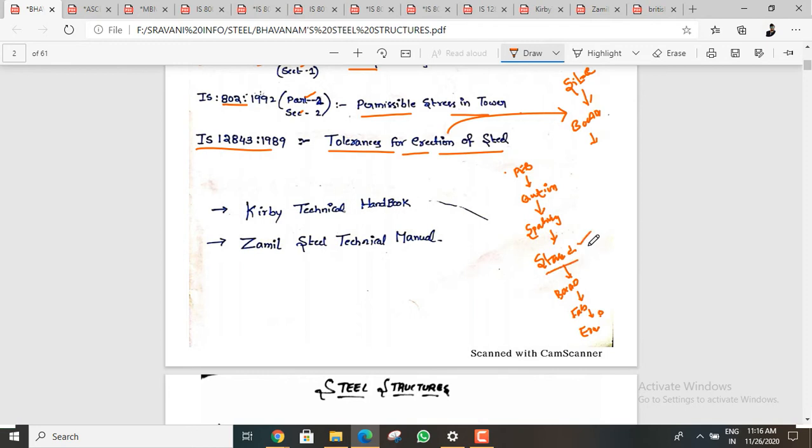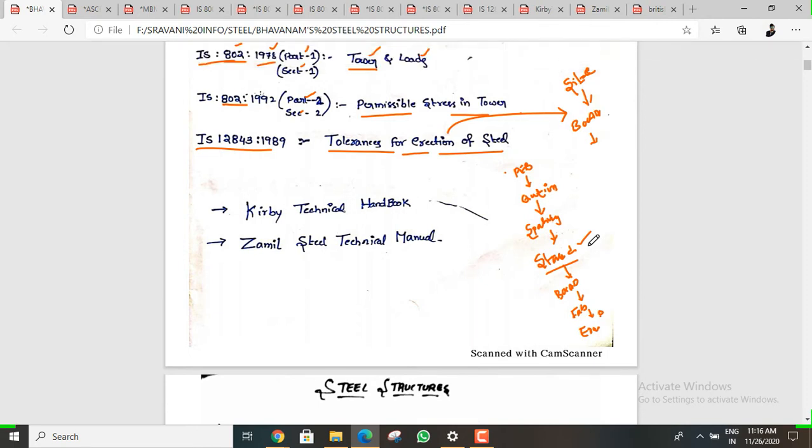You need to check that everything is correct, and that the structure is enough for carrying those loads, wind load and earthquake loads. And once the STAAD.Pro design work is done, the detailing work goes on. In BOCAD, we need to model a building and then do some error checks, to see whether the model is correct or not. And we need to make drawings for demo purposes. Just making one frame, we need to check whether the drawings come out correctly or not. Once it's correct, we need to draw the entire slab, the entire project.